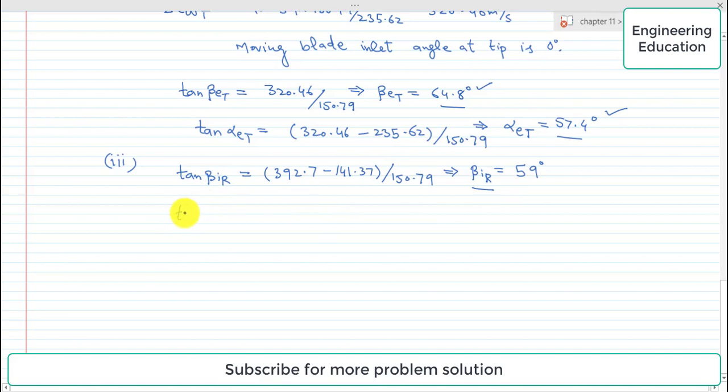Also again from the velocity triangles at blade root, tangent beta ER is equal to (534.11 minus 150.79 tangent beta IR) divided by 150.79.